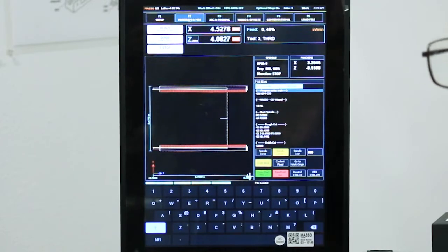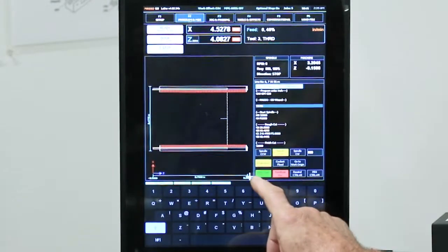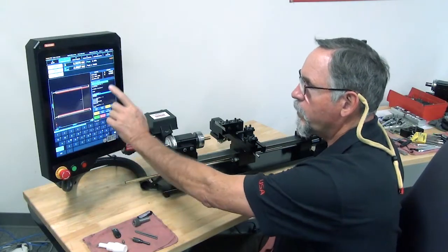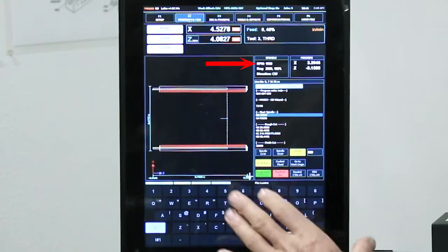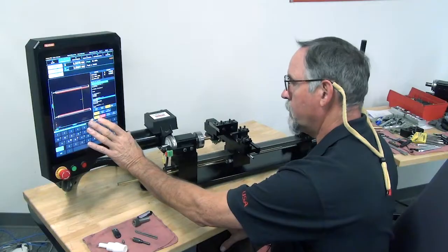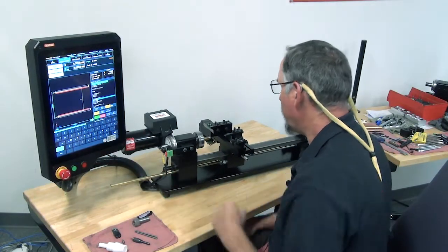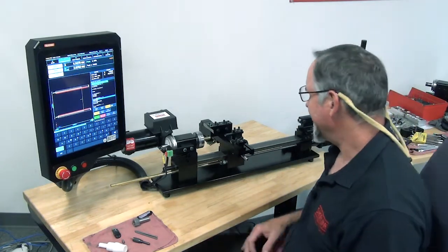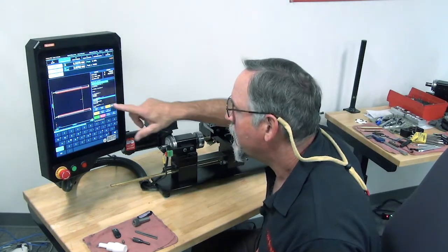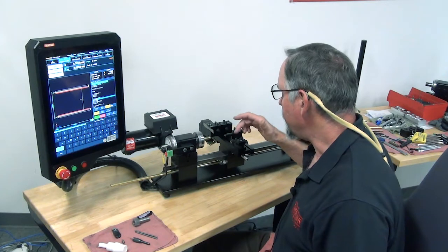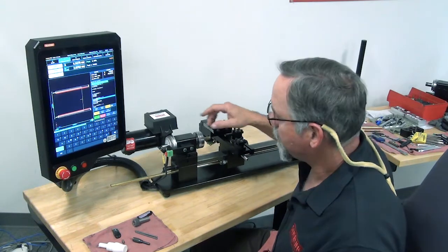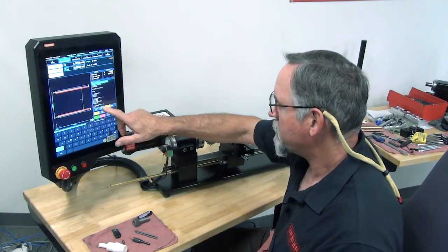So I'm going to go back to G code. We're on single block, and I'm going to start hitting cycle start. So my chuck is on. We're at 2,000 RPMs. Okay, so this is what I told you about. Right now it's going to Z of 50 thousandths. This should clear because this is sticking out further than this tool. However, I'm going to hit rewind and stop.